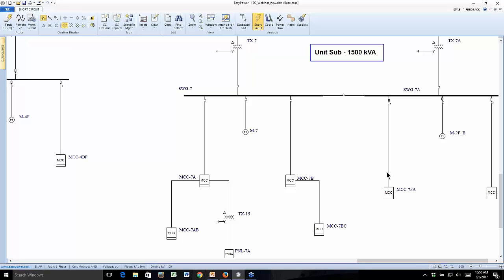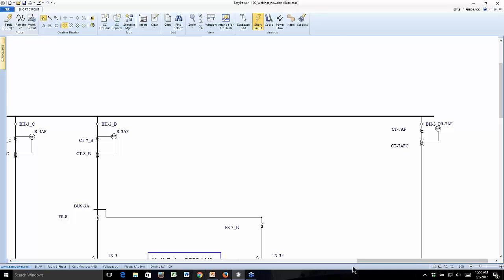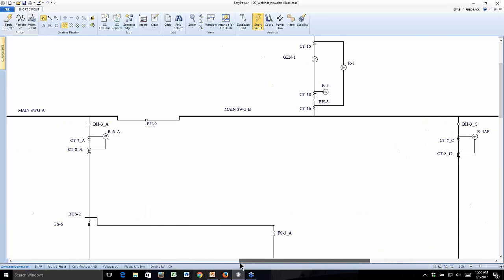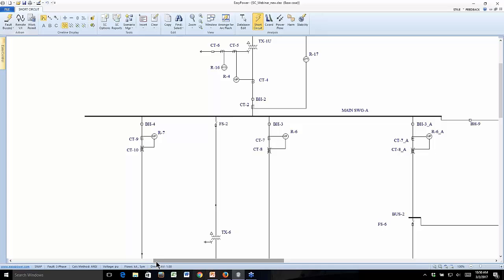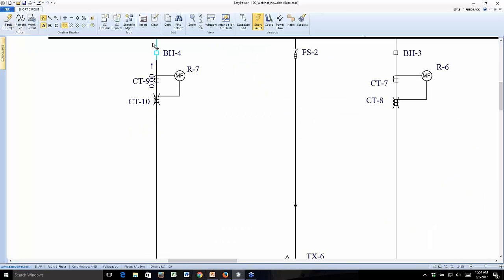All right, so the last thing, we've got a couple minutes, is the line-in fault. You may have seen that, this guy here. That really is probably not something you're going to use a lot, but the way this works is I'm going to select a particular circuit breaker, and if I do a line-in fault now, it essentially gives me the fault current coming back up this way as if this line here was open.